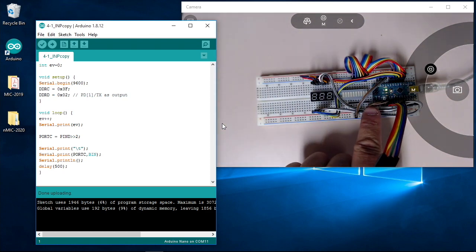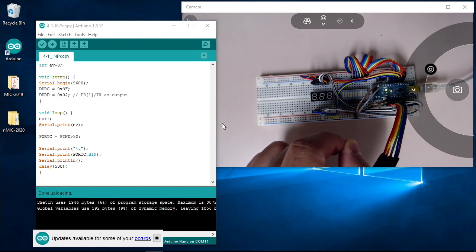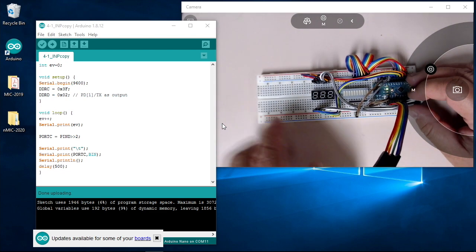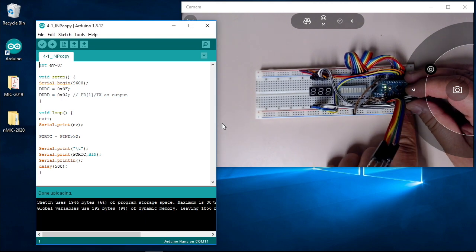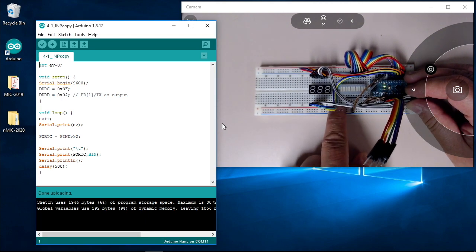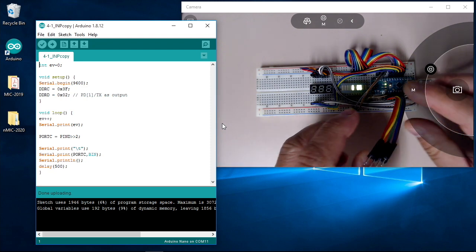Okay, that you can see. And the 5 volt is the system power. So on the board sometimes the middle is broken, so make sure that the two columns are not connected. If the marking, the red line or blue line, is broken, that means there are two separate sections of connection.